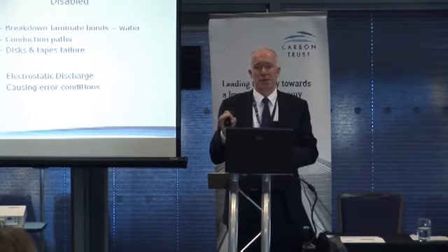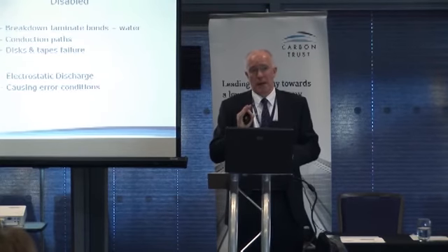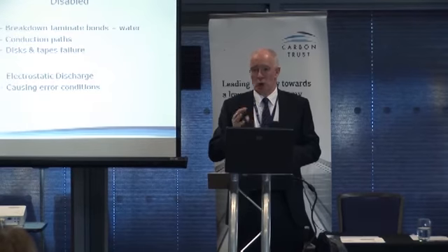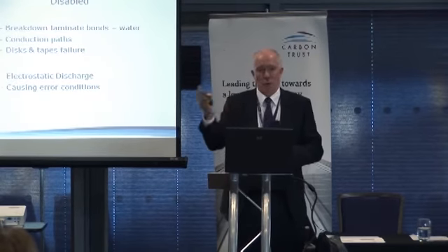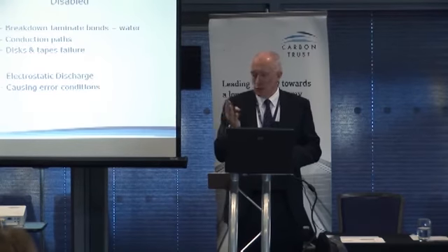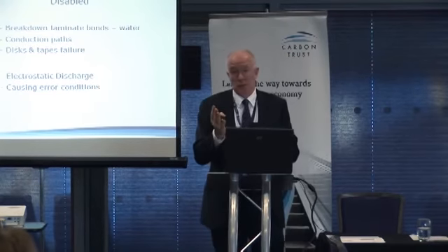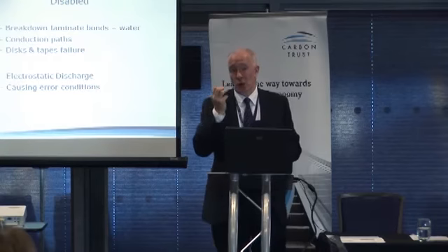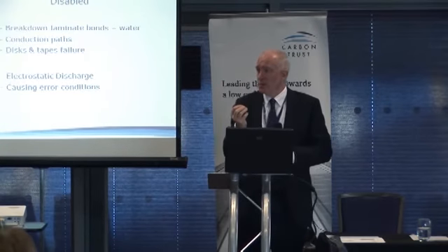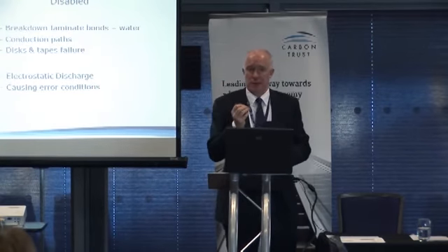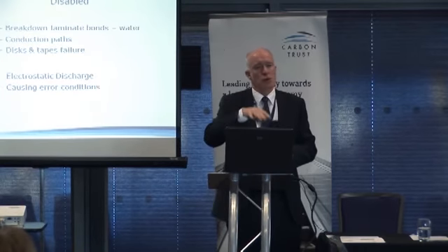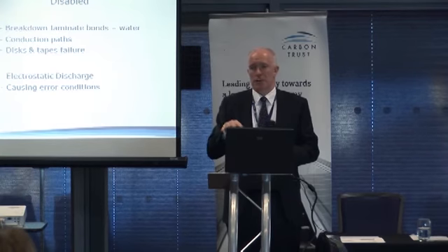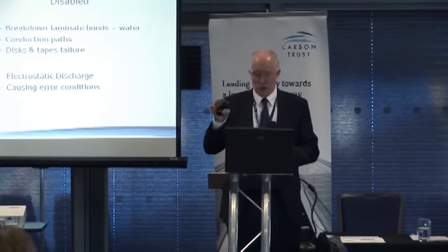The time for high humidity is when we're in the summer and it's pouring with rain outside. You've got hot, humid air that you're bringing into a computer room. If you've got fresh air coming into the computer room, we'll talk about this a bit later, that's moisture laden and hot, it may start to cause humidity precipitation on cold bits of metal, and that then causes problems. So most places are not controlling humidity now, and the majority are uncontrollable humidity, but just be aware of that problem.